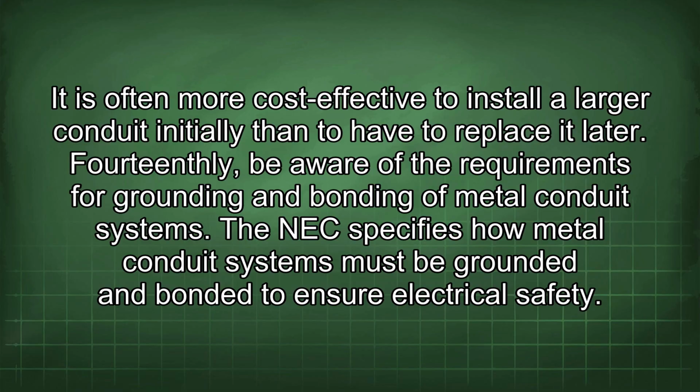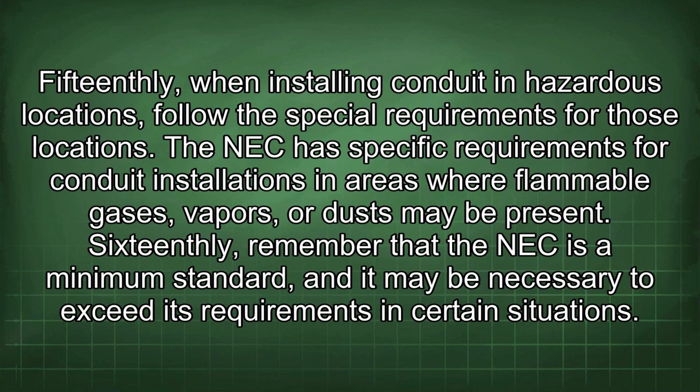14thly, be aware of the requirements for grounding and bonding of metal conduit systems. The NEC specifies how metal conduit systems must be grounded and bonded to ensure electrical safety. 15thly, when installing conduit in hazardous locations, follow the special requirements for those locations. The NEC has specific requirements for conduit installations in areas where flammable gases, vapors, or dust may be present.